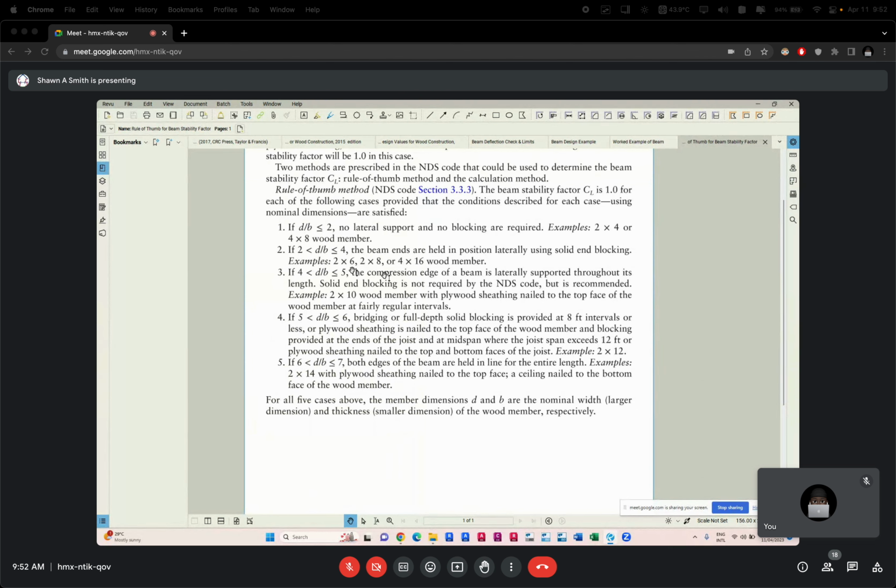All right. Similarly, the same thing applies to 4 by 16 and 2 by 6. And again, class, you can read point 3, point 4, and point 5, but please, these are your guide, because not in all cases will you be told that the beams are continually laterally braced by the flooring board or the plywood or the ceiling, whatever.